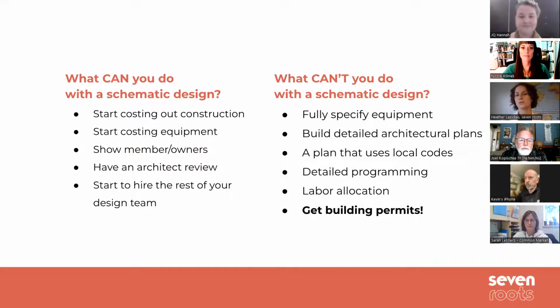What can't you do with a schematic design? Anything with details, right? We don't have the ability here to fully specify equipment, get really detailed with our architectural plans, or, again, Nicole said, this isn't fully up to code, detailed programming, labor, and most importantly, we can't get building permits, right? So you've got to go a lot further with a lot more detail before anyone's going to say, yeah, sure, go ahead and build this.